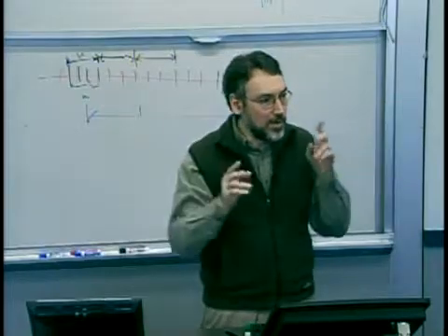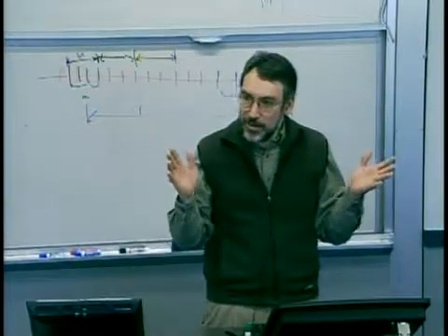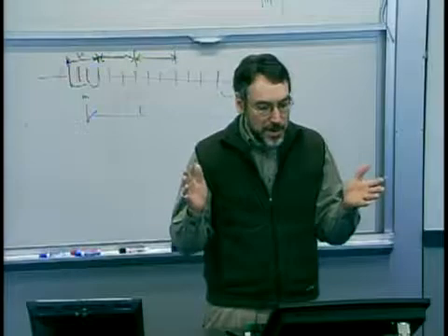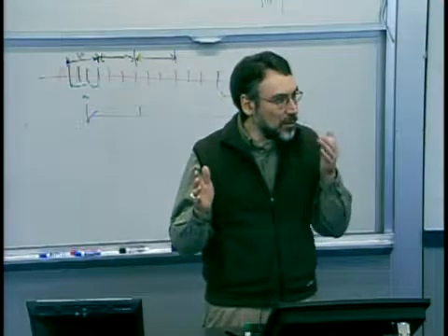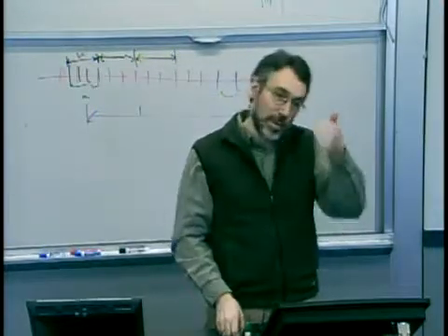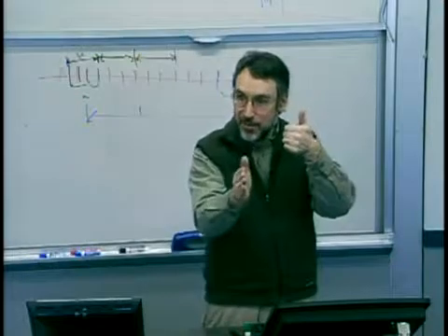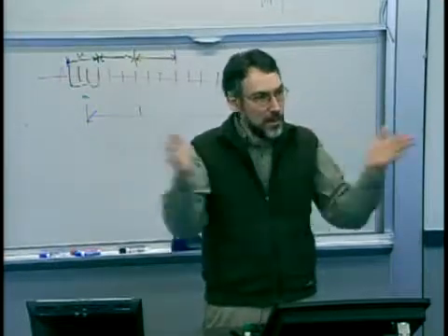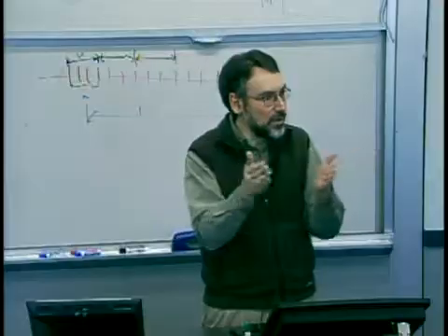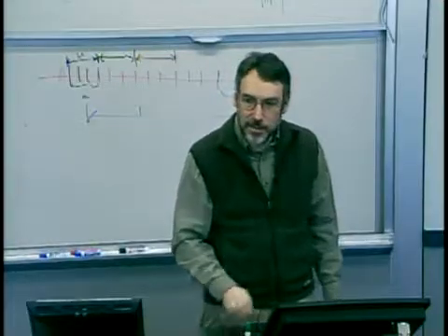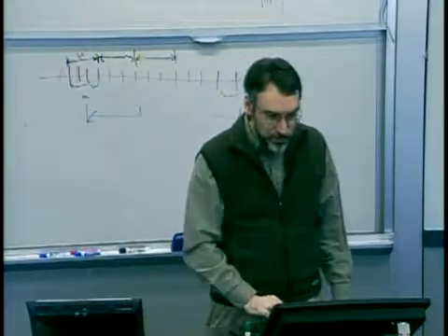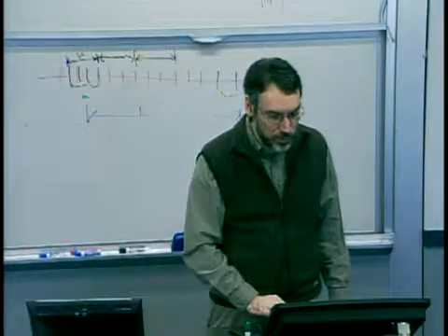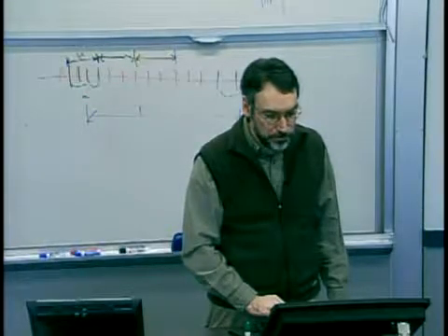So this really drives you to do two things, right? To minimize the quality loss function, what do you need to do? You want to target your process, get it mean-centered. And second, you want to reduce the deviation, reduce the variance in your process. So with one quality loss function, you're really driving the process towards both goals.